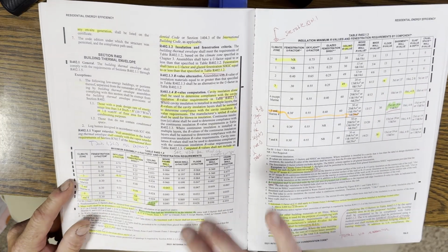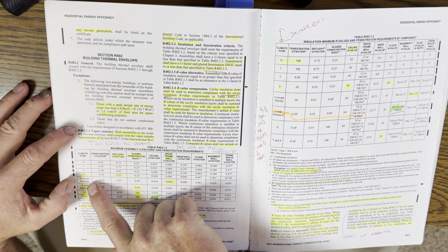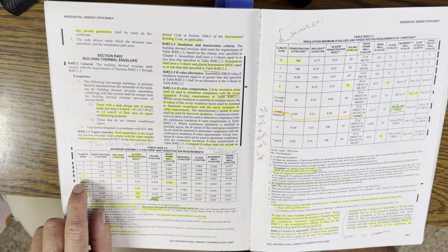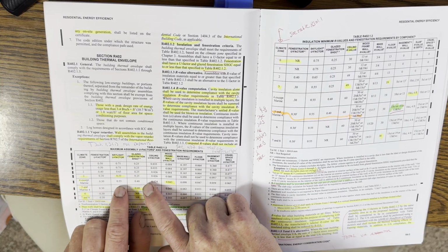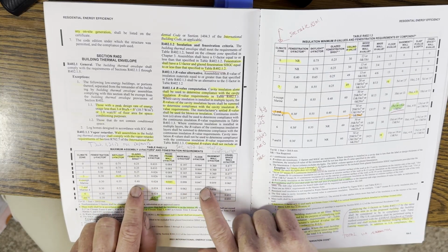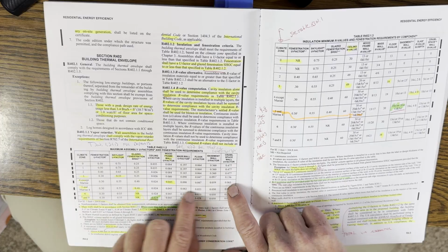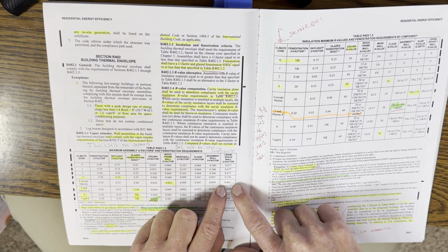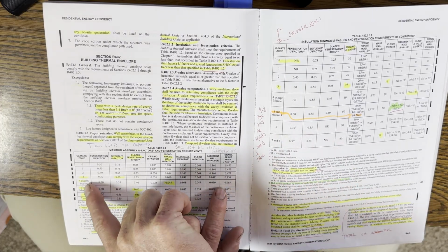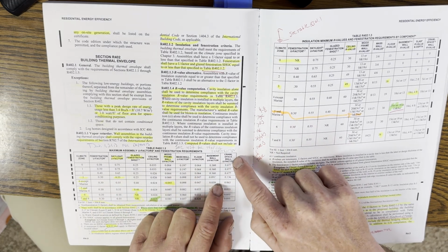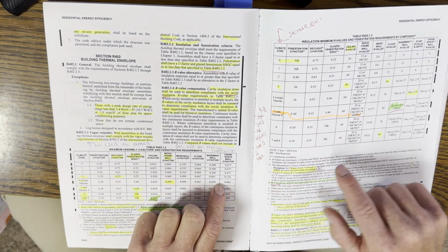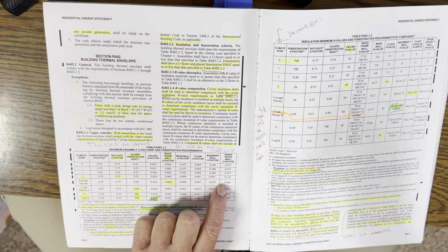Yeah, this threw me. This is one thing to prep on. I had a question. So climate zone 4. Let's see, what was it? Climate zone 4, but it was marine. This is climate zone 4 except marine, and it was crawl space wall U factor 0.065. And I didn't know what the answer was.